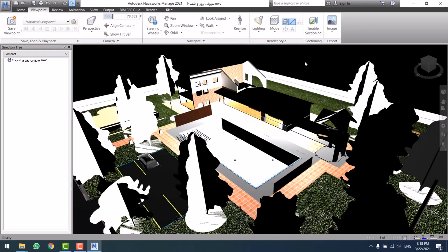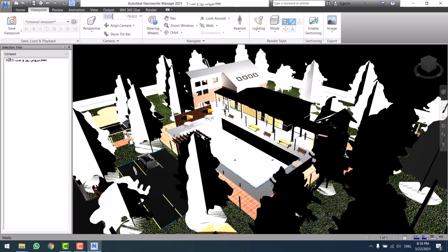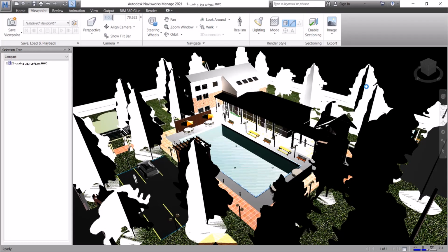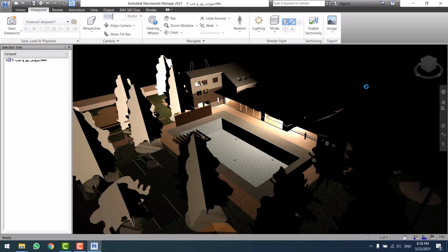So, continuing, let's see the changes. I don't consider this a proper lighting in my scene, since here we've got a combination of the lights from the native CAD file and also the 2 default opposing lights. And the last item is full lights. This mode uses lights that have been defined with the Autodesk rendering tool. So this time the default opposing lights are turned off, and we can check the defined lights in the rendering tool so that we can analyze the lighting in our project. Check this out, only the defined lights are on.